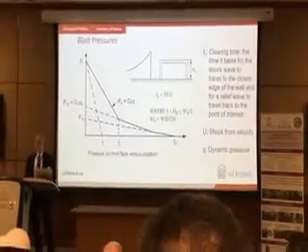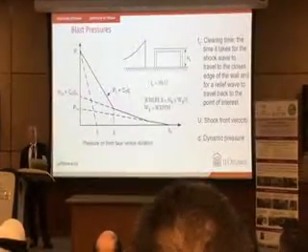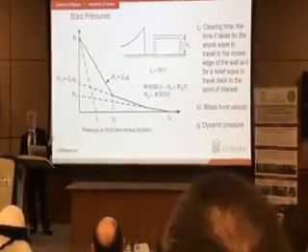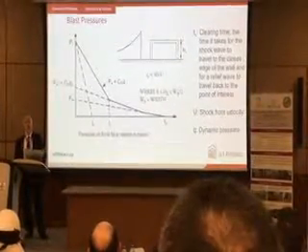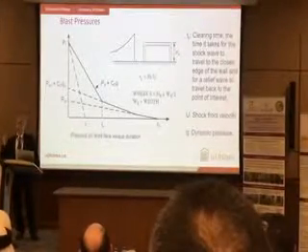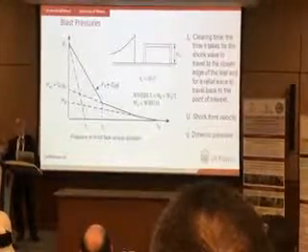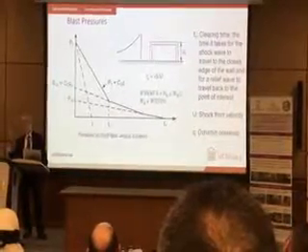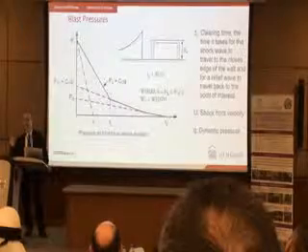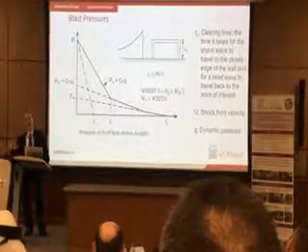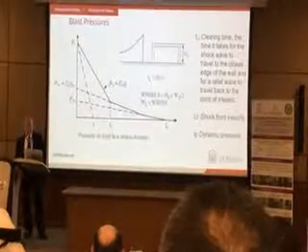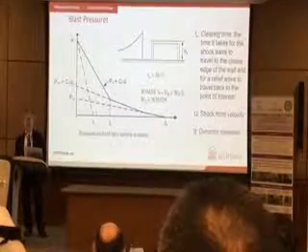There's another important aspect of blast pressure. I have given you the impression that pressure is probably the only thing that matters. That's not true. Impulse is another effect that affects building performance. So pressure and impulse. Impulse reflects duration of pressure, which is the area under this curve. Pressure versus time. So area under this triangular or bilinear relationship gives you impulse.